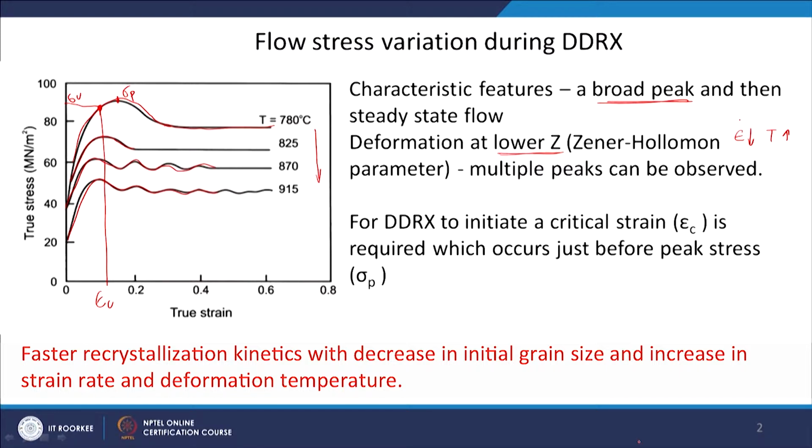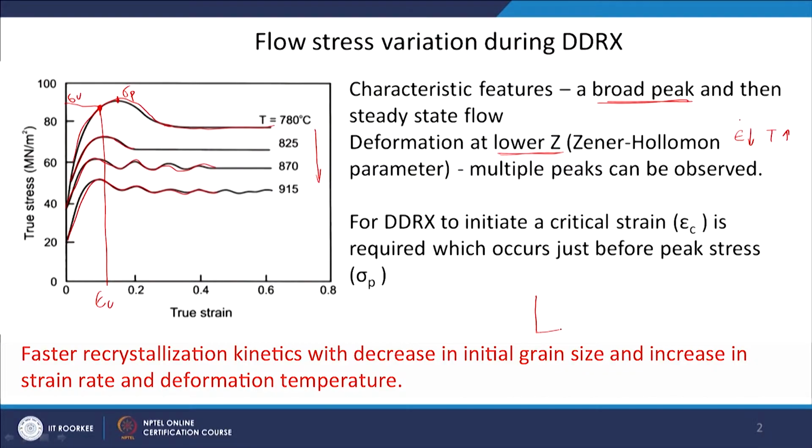Now recrystallization kinetics: kinetics means how fast the recrystallization completes after it starts. It usually also follows an S-shaped curve, as in phase transformation. If I have complete recrystallization here and 0 recrystallization here as a function of time, it will have a behavior like this, an S-shaped curve.